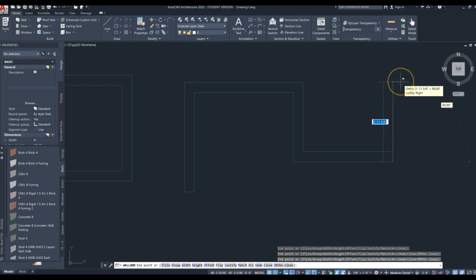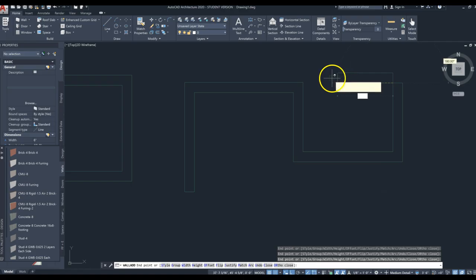You can change this. Simply hit the control button once on your keyboard, and it will justify on the other side. It'll measure the other side, and do all the calculating from the other side of the wall. So by hitting control on your keyboard, you toggle back and forth between these options. You may also see an option where you could justify center and measure the center of the wall. So that's a really handy tool, hitting control to change the wall justification.